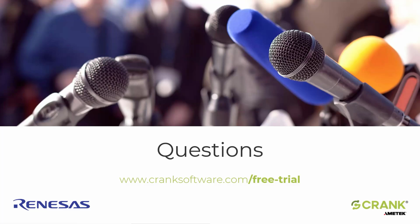Perfect. I have another one, Gary, if you want to keep going. It says, what is involved with porting Crank software to other target platforms? So essentially, it's down to the core. If you think of the various components, there's a runtime specific to the core, so Cortex M7, M33, M4, or whatever. The RTOS, so the kind of API for the system, and also whether it has any graphics acceleration or not. On top of that, we compile it with a toolchain, GCC or Keil or IAR.